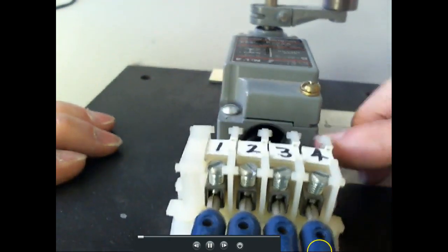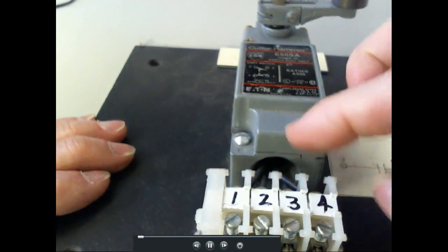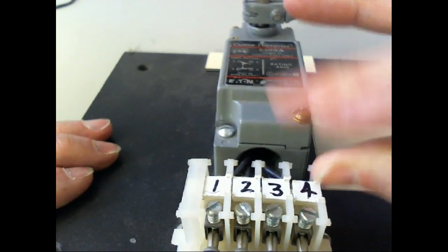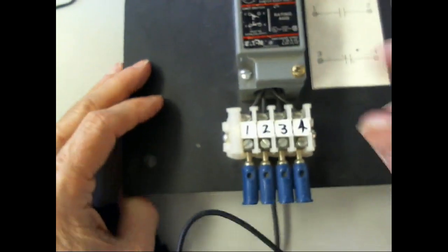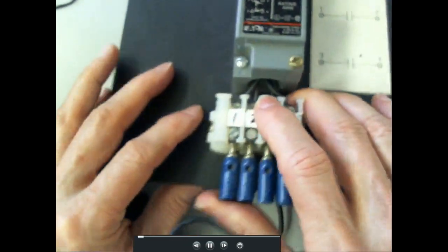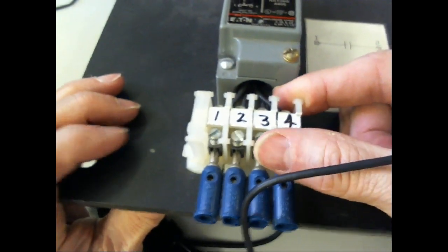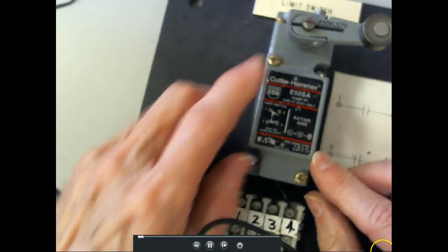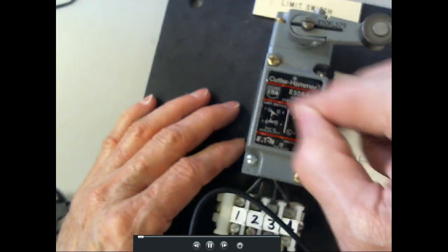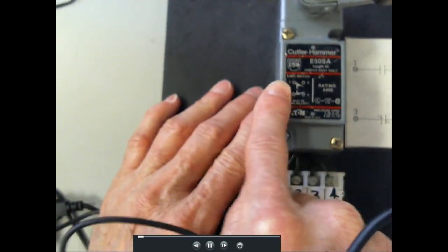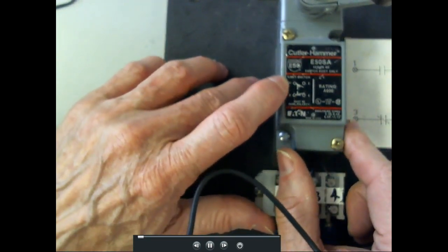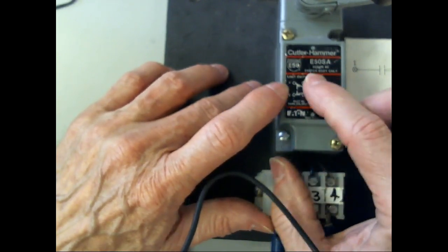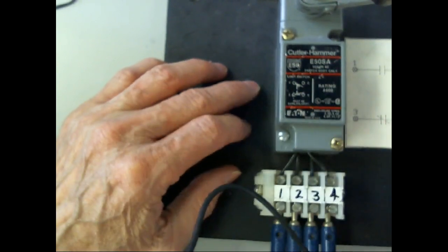So normally it has a screw-in on it, and then it's got a strain relief clamp that you have to clamp in. And then it usually has a rubber flap on it that seals around that. And that's going to prevent anything from getting in here. So normally what we would do is feed our wires up through here, take them through the clamp, and then take off this top cover, and then it's going to have the connections in here. Here are the actual manufacturer numbers on here, where I have, this is a double pole single throw, right? You understand that? I got one normally closed and one normally open.